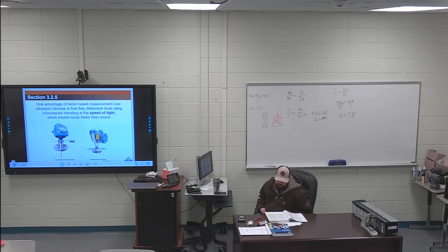So that would be like what you're using on that trainer out there. A bubbler system, 342. First sentence of 342 is highlighted. A bubbler system uses hydrostatic head pressure to measure level in a tank.